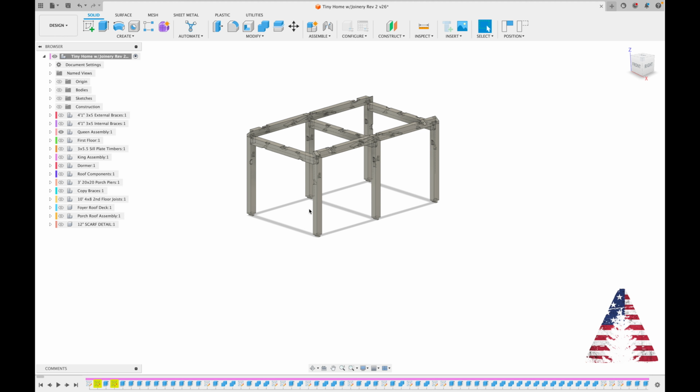As I mentioned, we'll call the x-axis from this side to this side. So along this beam's path is x, and then y would be along the purlin path. First we would assemble this purlin, attach these 3 posts, put in the braces, verify everything square, everything plumb, and then we can set this aside. And then we'll do the same with this side over here. These 3 posts, braces, square, plumb, set that aside.